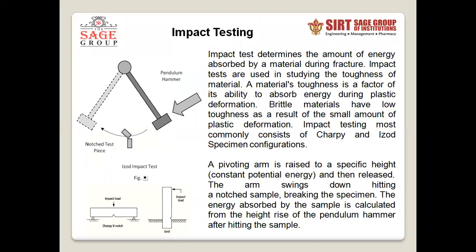So for testing the impact properties of toughness, impact testing is done, and the impact testing mechanism is very simple. In this, a pendulum hammer strikes the material to be tested, and the amount of remaining energy gives the idea of the energy absorbed by the material.